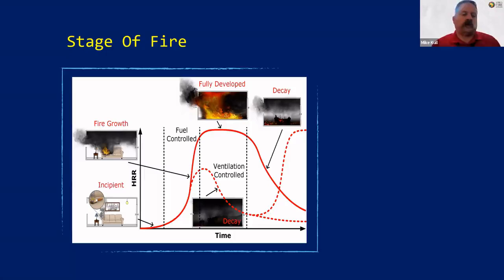That's the next step that we're looking at, where we've gotten through the incipient phase. During that incipient phase, right? There's not enough heat or flame to cause other things to collapse, right? And at that point, it's not really even causing other items within a room or something to catch fire. But then as it grows bigger and larger and starts producing enough heat, the fire begins to grow. So now we're in the growth stage, okay? We're looking at collapse potential, hazards to us in the building.